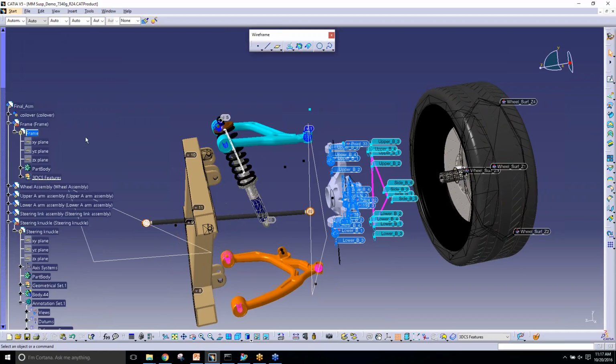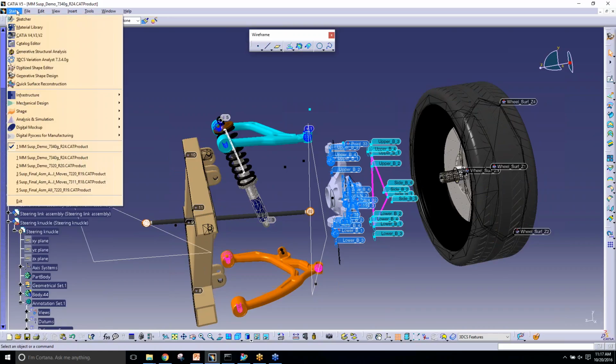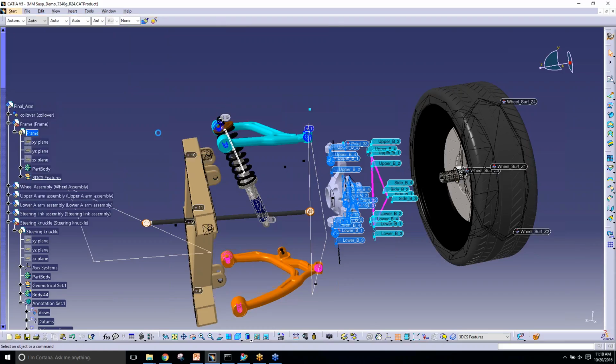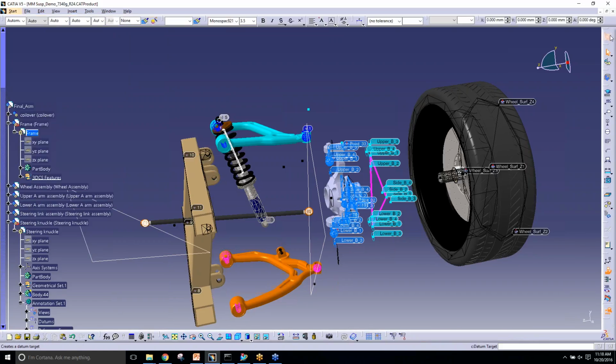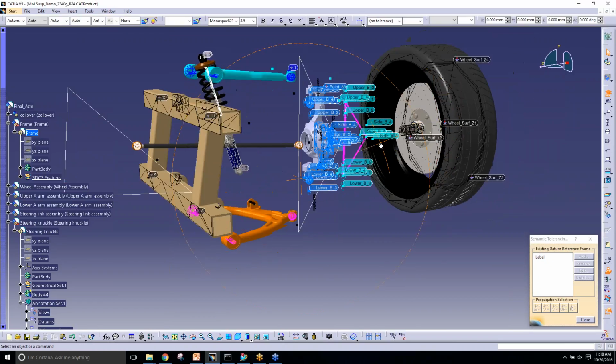So you're going to make GD&T in CATIA. Yep. And then you're going to pull that GD&T over into 3DCS. Correct. From CATIA. Yep. So now I'm going to switch over to my FT&A workbench. So function, tolerance, and annotation. And the dialog is called the tolerance advisor. So right now I have nothing in this frame. There's no 3D or FT&A.